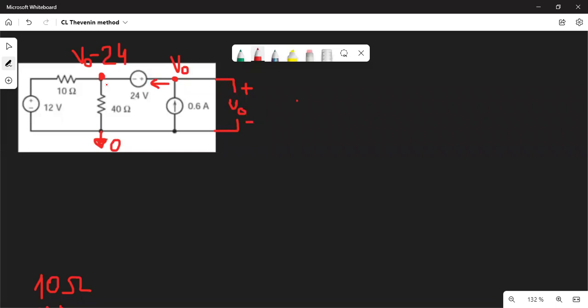So final node. For example, if you go from V0 minus 24 to the right, from left to right you get the polarity minus, and that means plus voltage rise. So overall, you will add plus 24 and again get V0, okay? So overall, when you meet the polarity plus, you subtract voltage. When you meet the polarity minus, you add voltage.